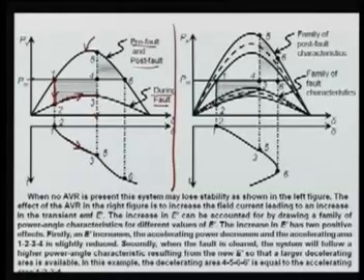Once the fault is cleared, this curve will jump to 0.5 because the post-fault condition is similar to your pre-fault condition. So it will follow the PE curve of the top one. Now this was accelerating, this was your A1, the accelerating area. Now this will try to go here and this is your area 2, and let's suppose your A2 here is less than your A1. So what will happen? Your system is unstable.